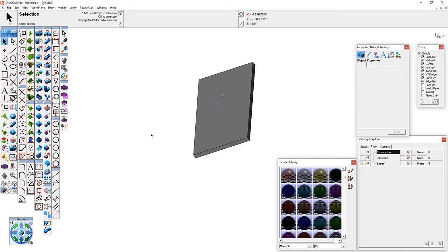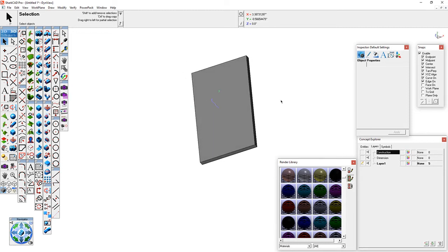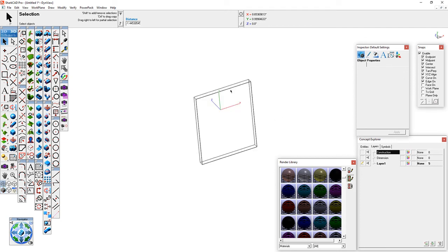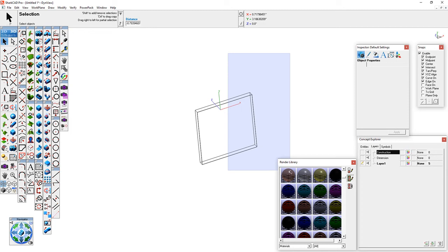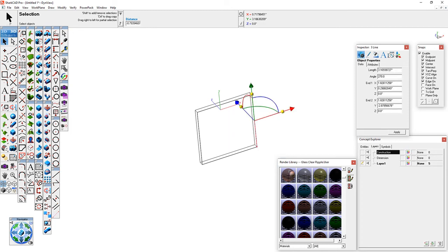This is very important. That sketch we had, it is basically connected to this box. So if I were to click that sketch and drag that line down, the box moves. Let's go back here. We're not picking the box, we're actually picking that line that created this box, and we're dragging it. So, and I'm making a box down and to the right.